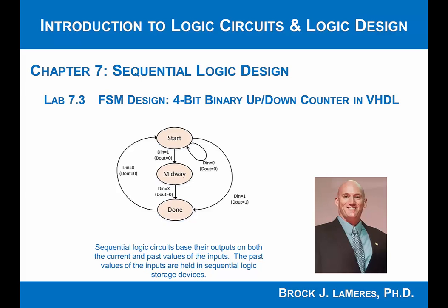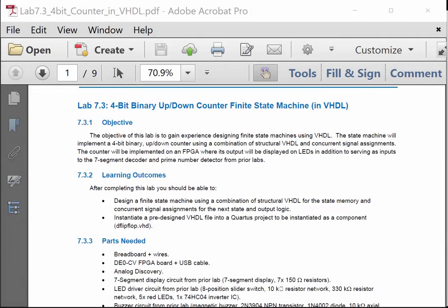In this lab exercise, we are going to build a finite state machine in VHDL, and we're going to use a combination of structural design and also concurrent signal assignments as the modeling approach. So what we're going to build is a 4-bit binary up-down counter.